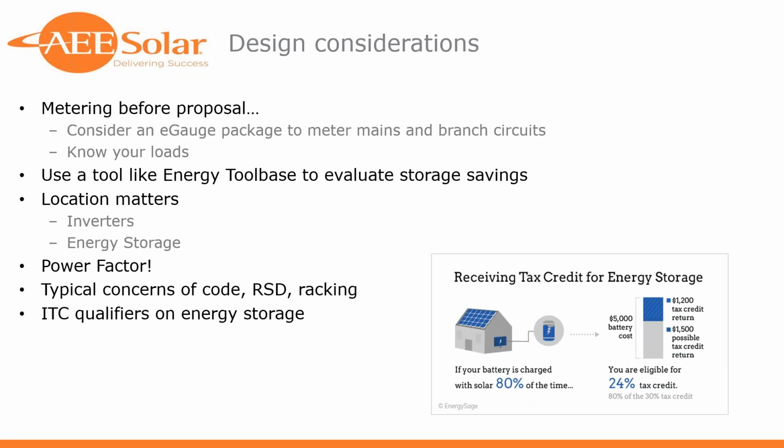Power factor. Not something we typically deal with in residential energy storage. I think for the most part, we're dealing with unity or close to it. We talked about manufacturing being the number one sector that these demand charge applications are being applied to. Incidentally, that's the sector with, on average, the worst power factor quality. So that's something you're going to have to take into account.